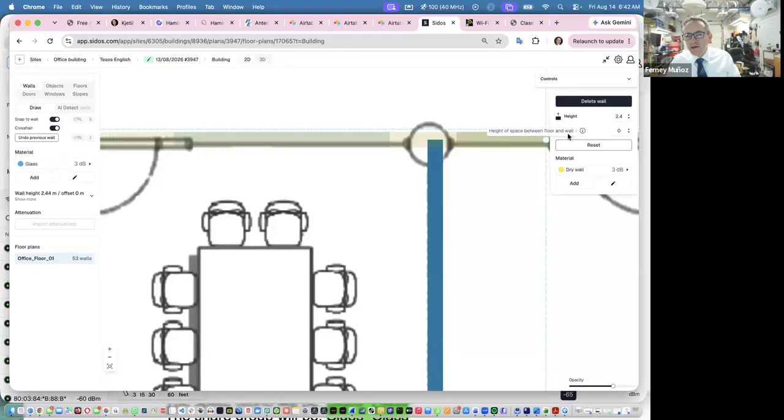Because in here, if I say the height of this wall is only 1.5 meters, see, now it lets me, because it's defining the height, and that's as high as I can go. I cannot go any higher than this from the ground, because the sum of these two has to be the height of the floor we define when creating the project.